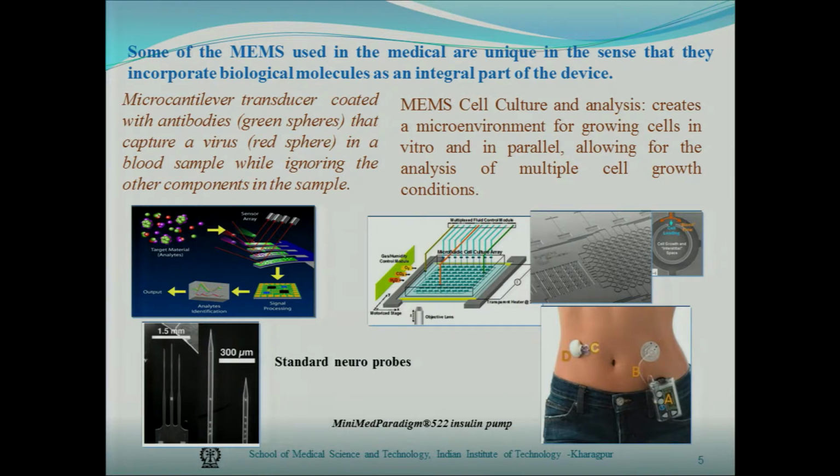Okay. And this can be made, earlier it was fabricated using silicon material at the initial phase, but silicon has a Young modulus which is much higher than the neurons, and when you just go and touch that, it may damage the neurons. So, what way we can avoid this is that I can have this kind of a needle using a polymer material, where the Young modulus of the polymer is compatible with the Young modulus of the neurons, so that the damages can be avoided. Okay.